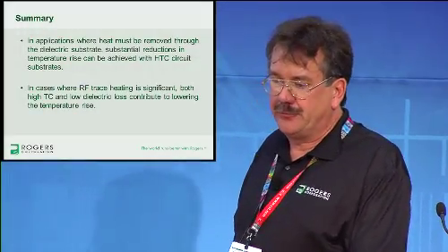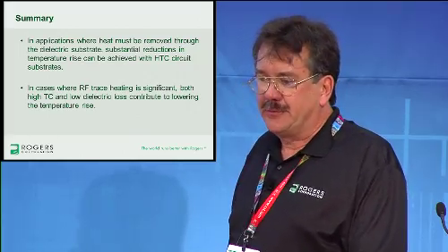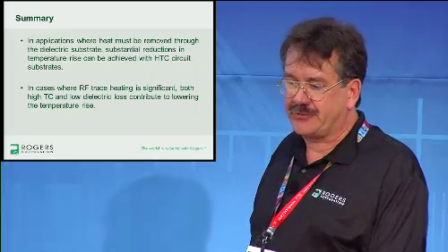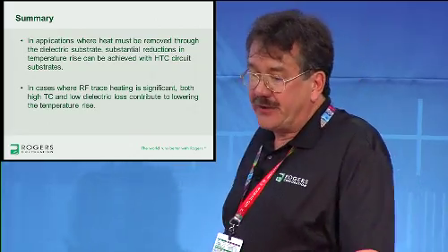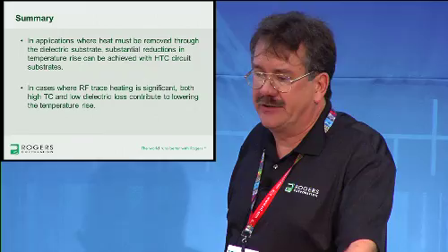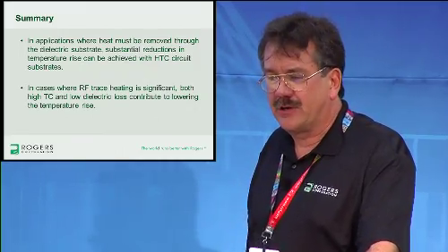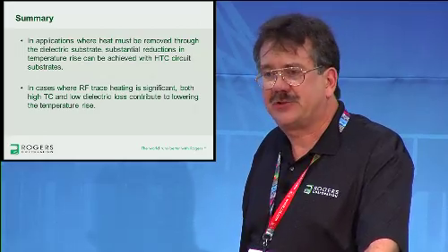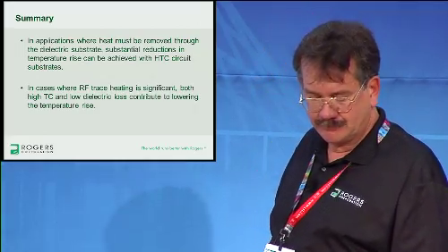So the summary here is, in applications where heat must be removed through the dielectric substrate, substantial reductions in temperature rise can be achieved with high thermal conductivity circuit substrates. In particular, in cases where RF trace heating is significant, both high thermal conductivity and low dielectric loss contribute to substantially lowering the temperature rise.